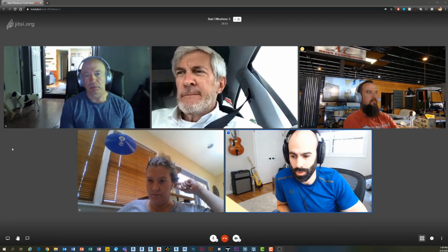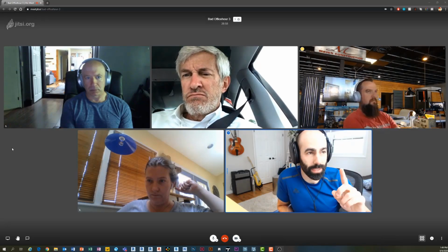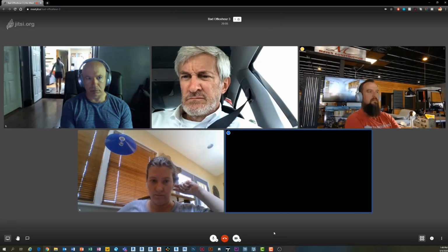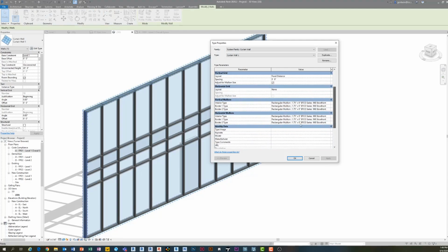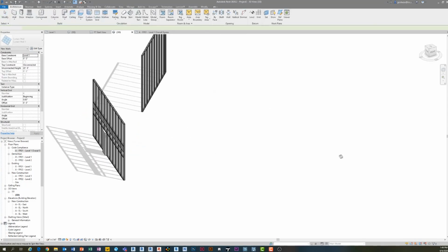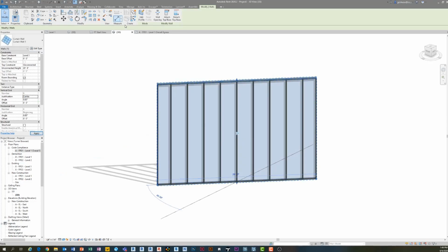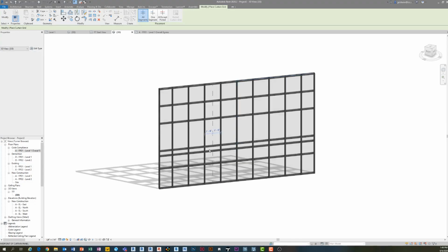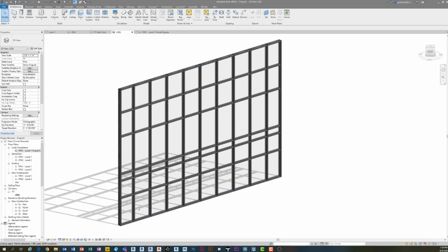It's a simple curtain wall with applied mullions and a vertical spacing, no horizontal spacing. But the key is you notice how I assigned, even though I didn't have a spacing for horizontal, I still assigned mullions to horizontal. Because now when you place this, it's going to do your verticals, and if you want these to be centered, or end, whatever. But now whenever I place a grid line anywhere on that, it's going to apply the mullions that I tell it to, because they're horizontal. Makes it much faster to create things.